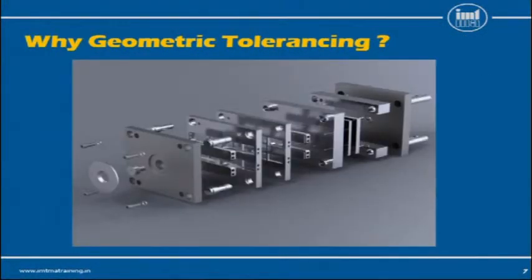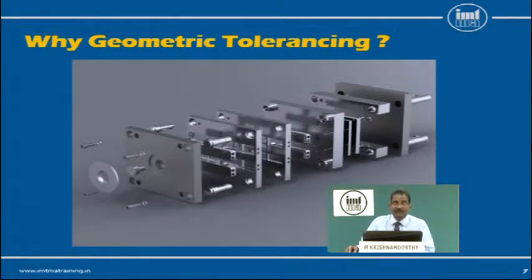Multiple plates are there, right from bottom plate to top plate, through cavity plate, core plate, etc. Even here the parallelism of the individual plates are very critical. The alignment of the guide bush to the core plate and the alignment of the guide pillar to the cavity plate are important to have a uniform closing and opening whenever the mold cycle operates.